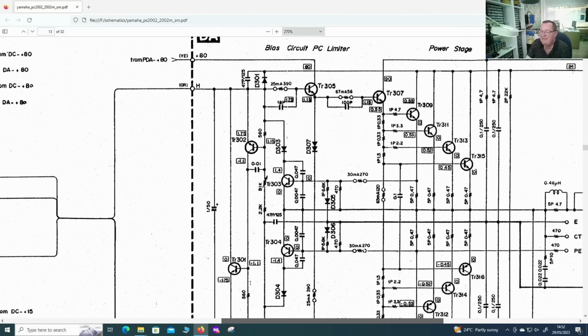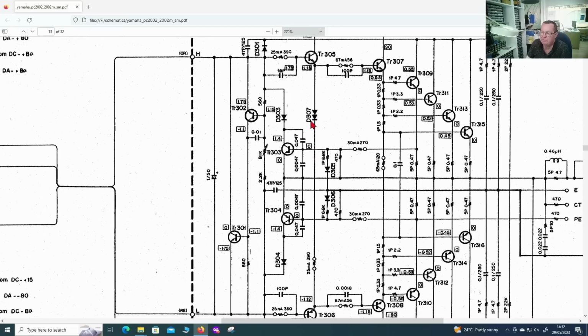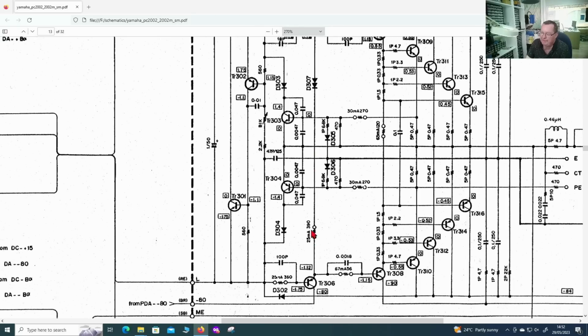Do I see any in here? Well, you can't go this way because there's a diode, a very funny looking diode, but there's also a 390 ohm resistor, so it can't be going that way, even if that then could have a shorted transistor and come back to ground. There's no route there.